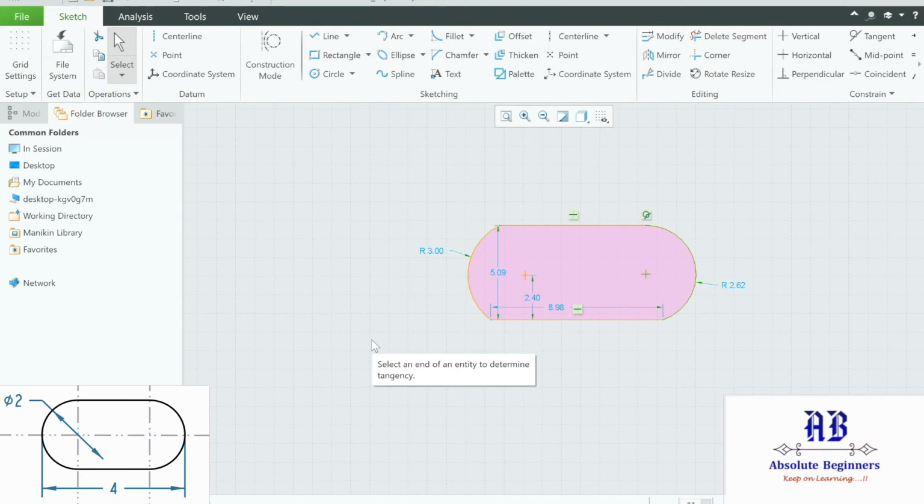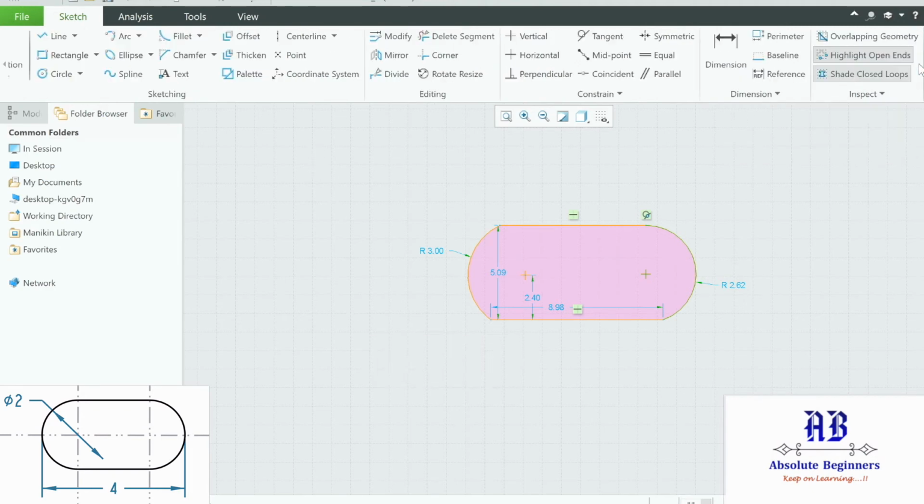Now step 2 is to specify all dimensions provided in your drawing, but we do not need to give exact values of your dimensions. What does this mean? I'll go to dimensions. This is one dimension that is provided to me in the drawing. I can click on it and make this a radius dimension, but what I need is a diameter dimension.